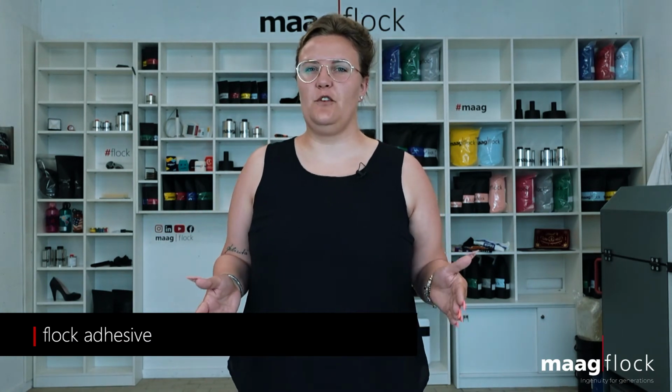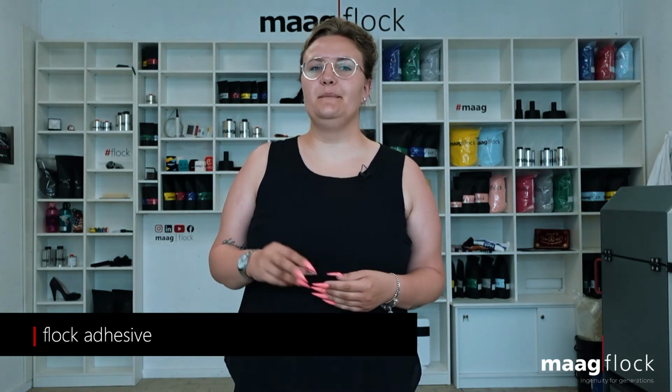In addition to flock fibers, we also need an adhesive for flocking. A differentiation is made between two types of adhesives, solvent-based and water-based adhesives. Solvent-based adhesives have better adhesion but are more harmful to the environment, pose a health risk and are more expensive to produce and above all to dispose of. Water-based adhesives are more environmentally friendly and are easier to dispose of, as they are disposed of with residual waste